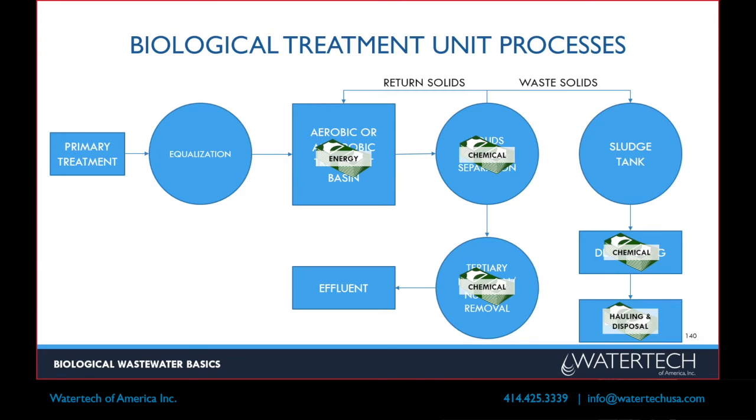This is a real sensitive part of the process, because if you don't have tertiary filtration, then you're going straight from your solids liquid separation into your effluent. So if you have filamentous bacteria and you can't settle, then you're at a risk of violating your permit, because you're going to have solids carry over and go out. And so they're really susceptible to upset.